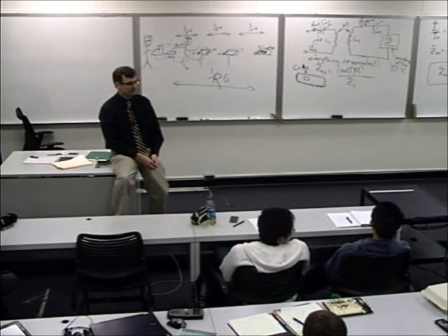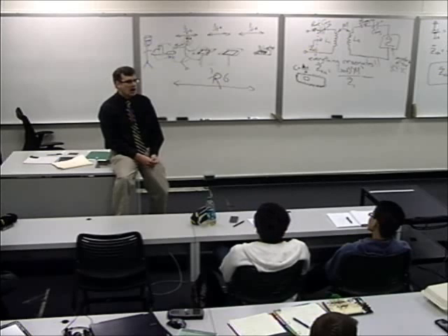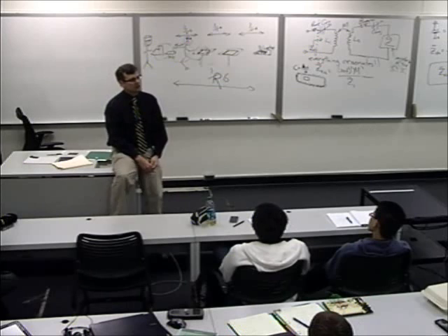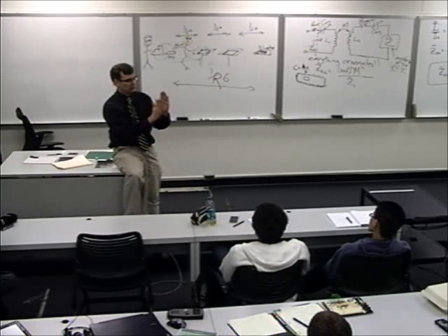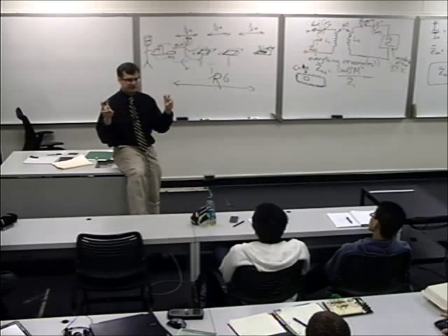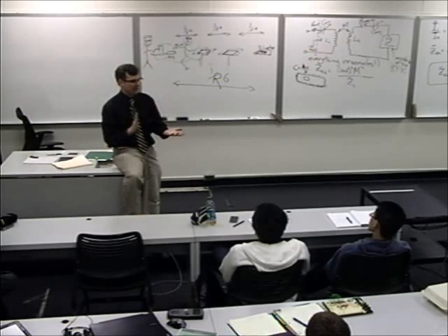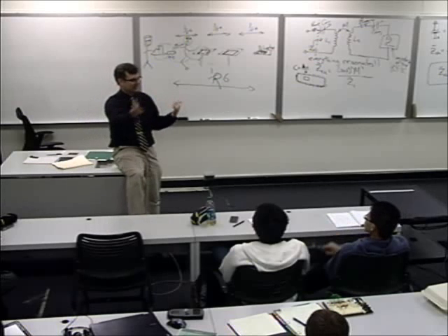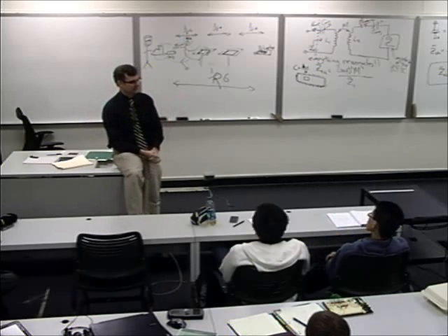Why is it 13.56 megahertz? Why is that frequency? There is the short of it. There are several discrete bands that you can use for what's called Part 15 unlicensed intentional emitters, and that happens to be one of them. It also happens to be high enough in frequency where you can get really good coupling, but you're not into these radiated modes and lossy electronics. It's kind of a sweet spot.